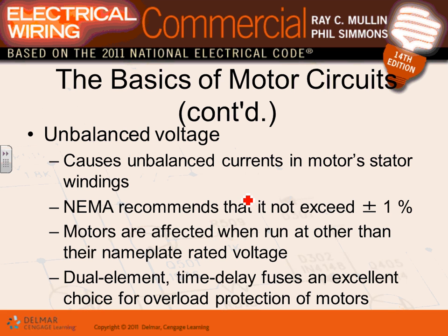A third phase, guys, how do you create phases? You have coils. You manipulate the magnetism to create a third phase. And what are motors? Motors are coils. So you could easily create another phase. Now, here's the question: is this phase as good as the phase that they give you? Absolutely not. Is it efficient? Not. Does it work? Yes. Does it work efficiently? Absolutely not. Does it give you the full power? No. But would it run slightly? Yes, small loads and so forth.